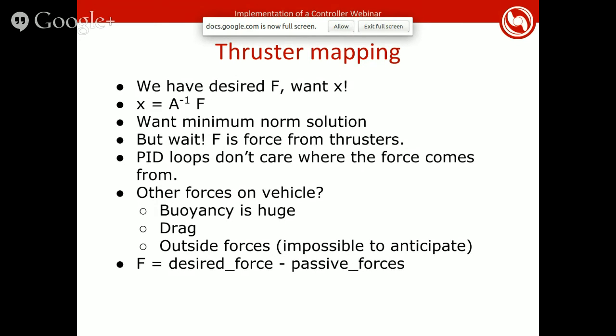But there is a catch there, because, of course, your thrusters aren't infinitely powerful. The solution returned here might give you a force for a thruster that thruster simply can't provide. So if your thruster, say, at full power provides only 5 newtons of force, and a certain desired torque and desired acceleration requires that particular thruster to output 7 newtons, well, you're kind of screwed there.